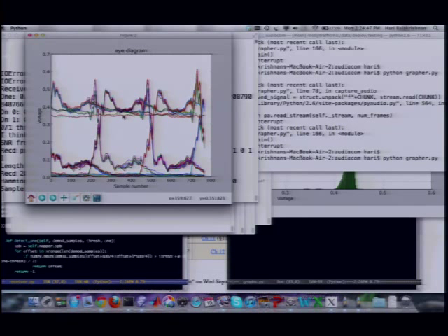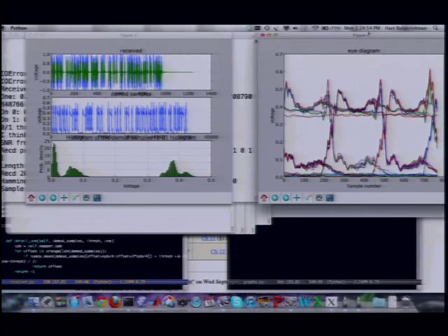But the point is that when you see the separation and you see a point in the middle here with a big gap on this eye diagram graph, and then you see a separation between these were the zeros and those were the ones, which means you could threshold somewhere in the middle and separate out which bits were zeros and which bits were ones, it means you're cooking. Things are great. Okay? So you can see that there's some distribution here of what the ones look like in the empirical data. There's a distribution here of what the zeros look like. This is not going to be a Gaussian at all. I'll explain why that is in a moment.